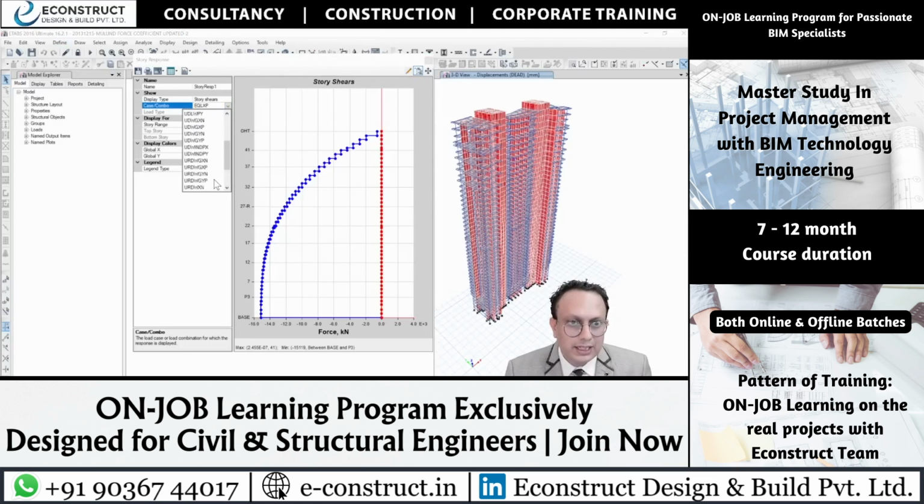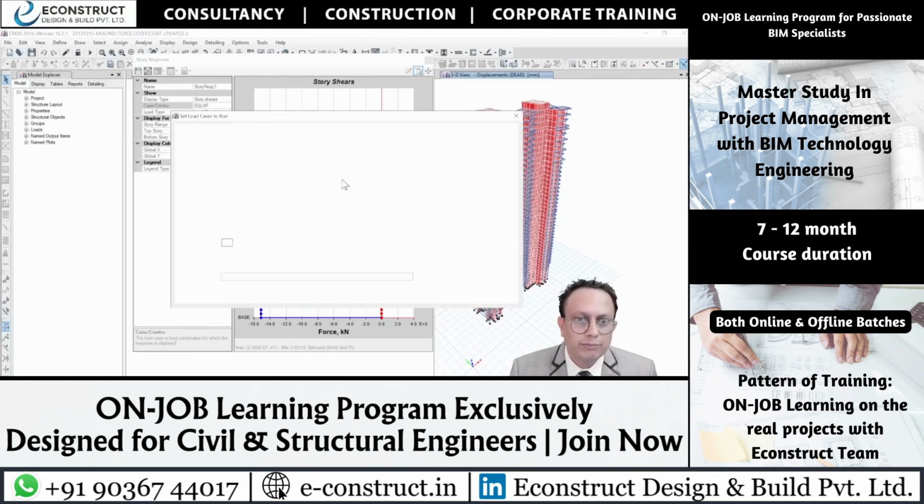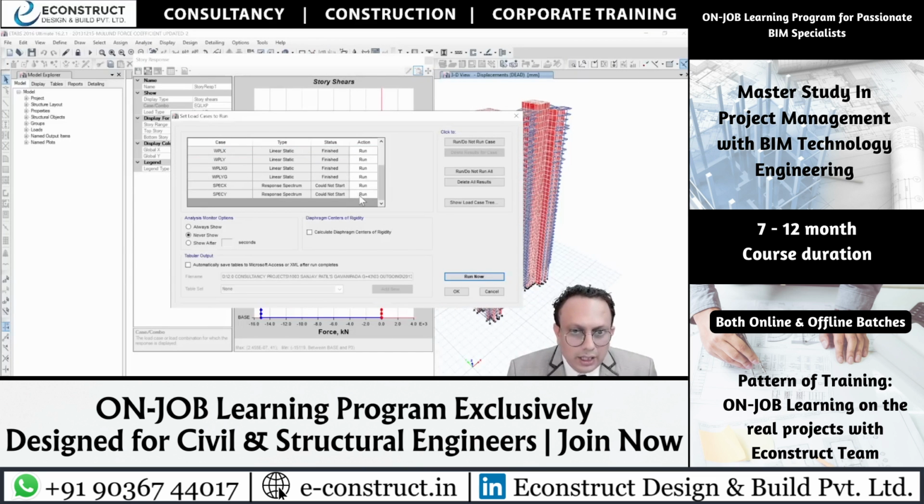Now we will see the dynamic analysis forces also. So I'll go to the dynamic analysis forces. I think I have not analyzed it by now. But if you take the dynamic analysis forces, you will see that the base shear of the static and the base shear of the dynamic should both match with each other. All right.